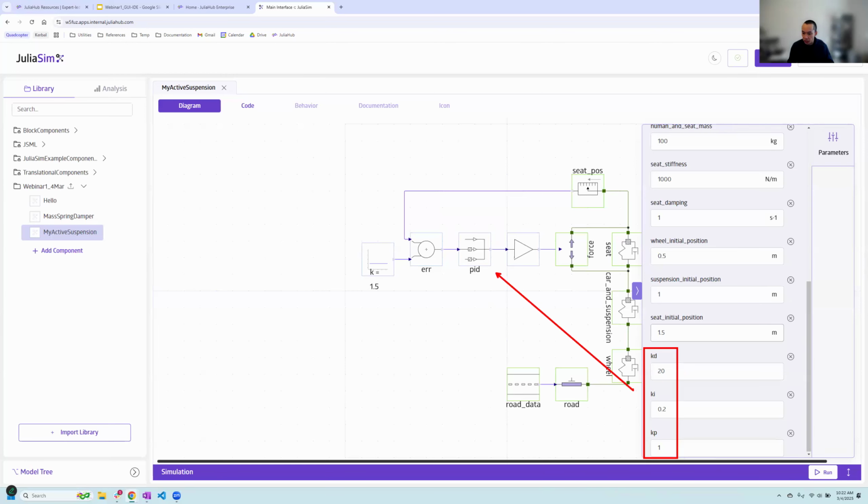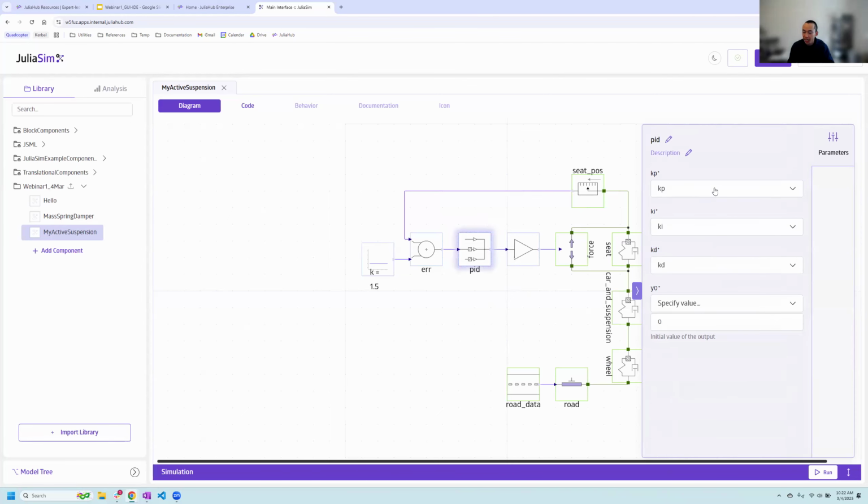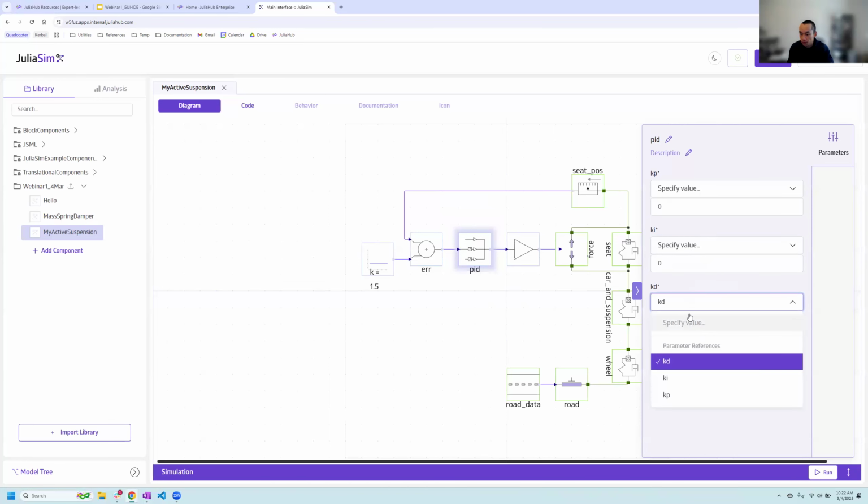So if I want to set all these values equal to 0, I can choose to do it here at the parent level component. But I don't want to lose these values. So instead, I'm just going to go back to my PID block. And here, instead of using the default values, I will specify my own values within the PID block right here. And the value I'm going to specify for each of these gains is, of course, 0. Okay, there it is. So now we have this set up properly.